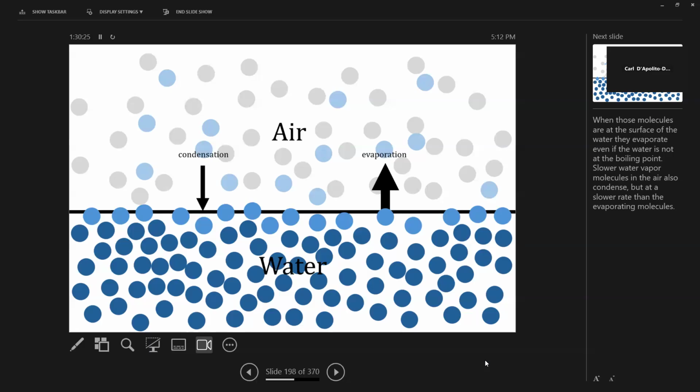The maximum amount that the air can cool through evaporation is what's called the wet bulb. So the dry bulb, the coolest the air could be through evaporating, is what's called the wet bulb temperature. It's sort of confusing, but if you had a really good swamp cooler or a really good fountain, it would just cool the air until it was full of water. And that is the wet bulb.